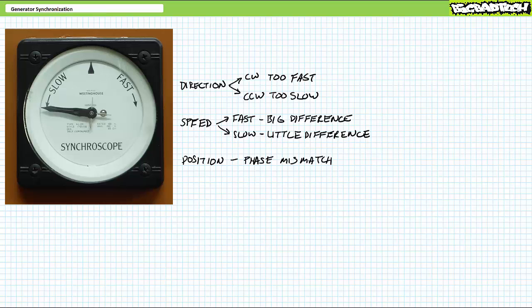If this all seems like too much to manage with too big of consequences if you get it wrong, you're not the only one. For this reason, automated synchronization methods exist that do not rely upon the subjective interpretations and shortcomings of dim-witted human operators. We'll examine closed-loop controls and protective relay schemes in much later lectures that make use of a synchro check relay, which, as the name implies, permits synchronization only when certain circumstances, i.e. matching voltage, frequency, phase, and sequence are met.